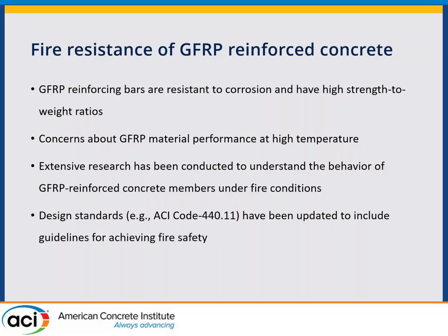We're all here because we know about the wonderful properties of FRP, the high strength, resistance to corrosion. One of the challenges when you're dealing with elevated temperatures or fire concerns is that there is a reduction in capacity of the GFRP materials, and so we really have to take that into consideration with our designs.